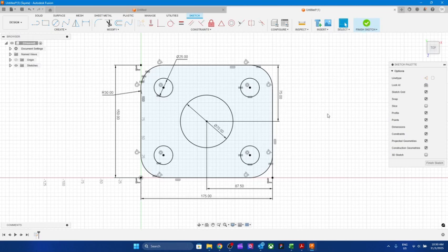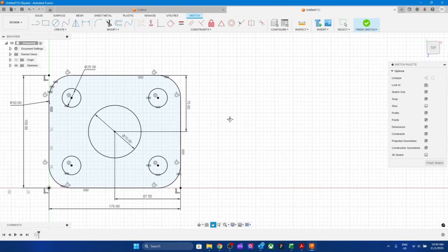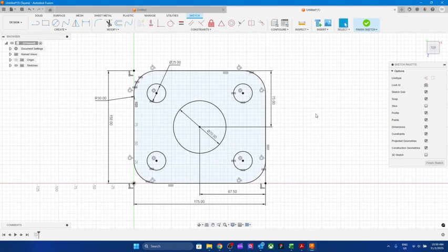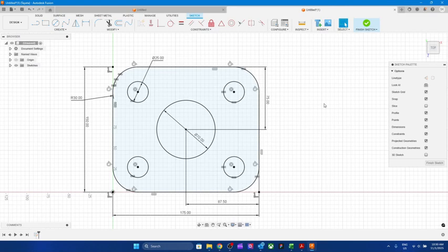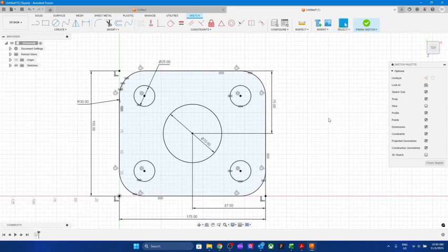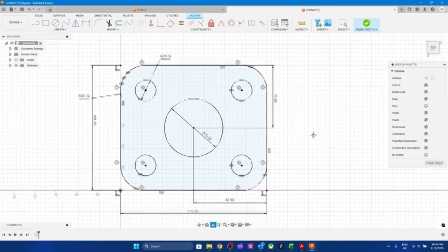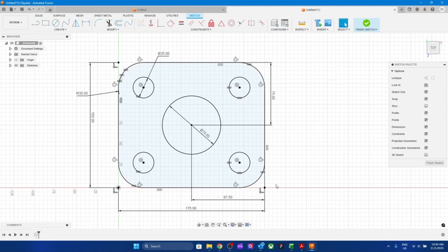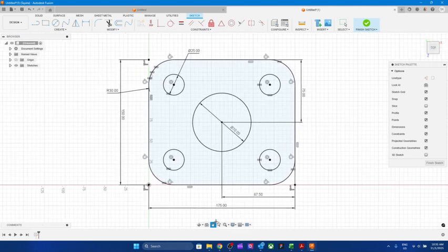Doctor, I'm sorry. For the wheel, how are you panning without changing it from 2D into perspective? What do you mean? How am I panning, moving? Yes, because when I do that, it changes into perspective. Oh, okay. If you just press the mouse wheel somewhere here, nothing else, you'll be able to move. Can you try? Unless your mouse wheel setting is different than mine. Or if you can't move, just select pan and you'll be able to do that. You see there's a hand.